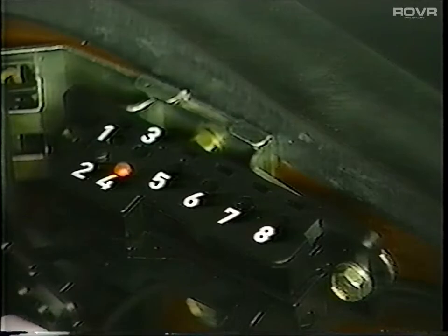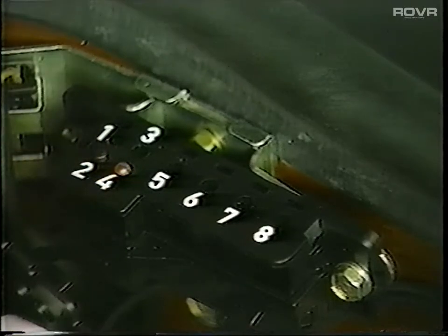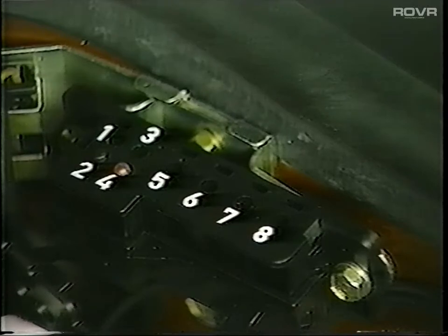The key feature of this diagnostic system is the ability to initiate a test by simply pushing a button provided for this purpose and reading a blink code. The number of blink impulses, which may be as high as 12 for a V8 engine, are listed on a diagnostic table with the related fault.